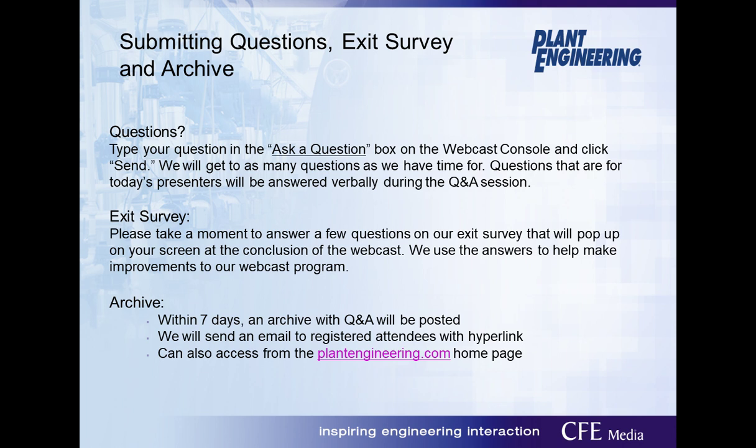If you don't have a meter, you have load/unload machines. Time the cycles to see how much you're loaded and how much you're unloaded, because the loaded time versus unloaded time will give you the percentage. So it depends on the type of air compressor; this is what you do with the leak load and how you do it.